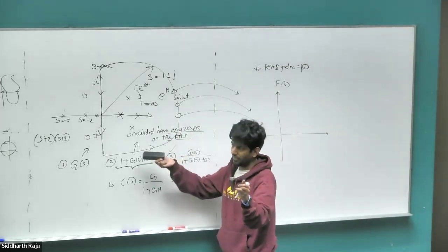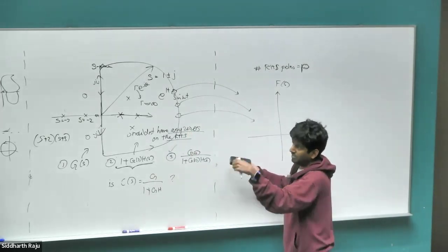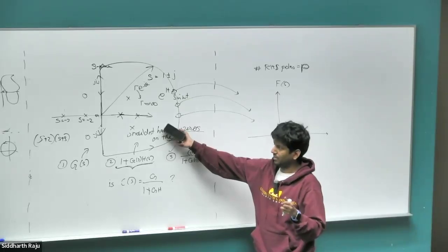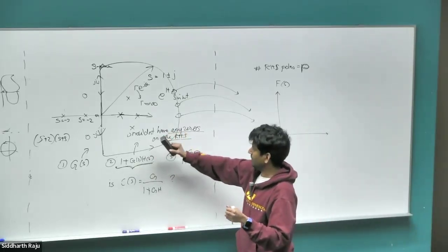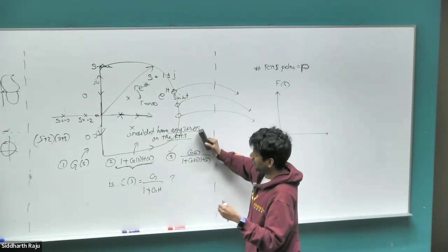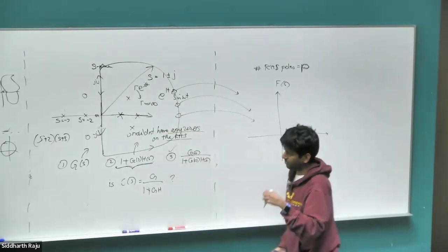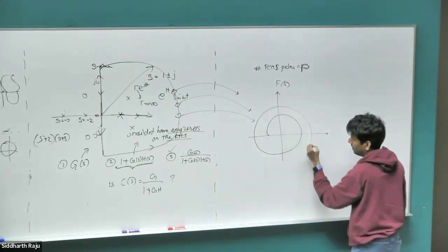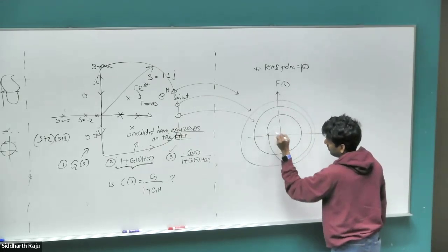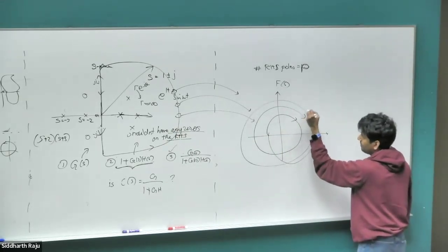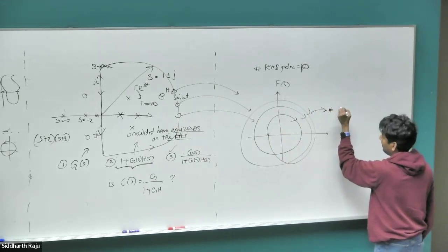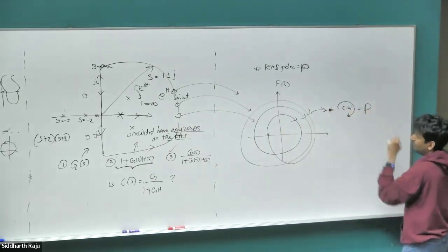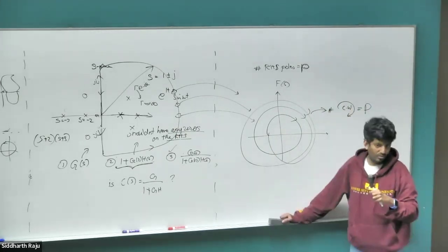There is no purpose even analyzing the system. We started off with a stable motor. If we design a control system and make it unstable, then we are just bad designers. So we are going to design a system that doesn't have any zeros on the RHS. Now we are going to see what would happen if there are any poles on the RHS. Well, if there are any poles, then it would encircle the origin, and the number of times it encircles the origin in the clockwise direction would be equal to P. Right? Everybody clear so far?